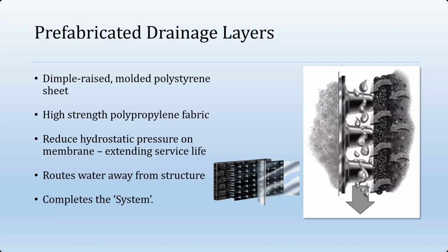And another point could be if we place the drainage mat on the outboard side, it's a lot easier to integrate or incorporate this with the drain tile system below it. If we go between the insulation and the waterproofing, it makes for a little bit more challenging application. Now, consider in a waterproof horizontal deck, there's a particular manufacturer of extruded polystyrene that makes the familiar blue stuff. Their warranty position will not be honored for thermal warranty of their insulation if a drainage mat factors underneath the insulation. There's a technical bulletin I have a copy of if anybody's interested in that.